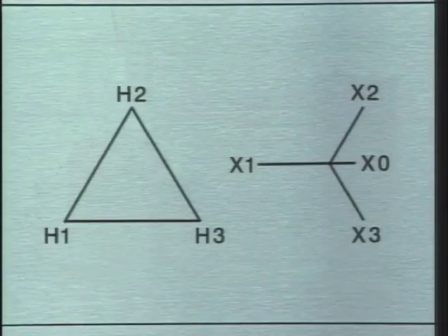In this part of the program, we're going to look at the principles for determining where to make the test connections to test the turns ratio of a given transformer. The transformer example that we'll use is a delta Y power transformer. The key to determining where to make test connections for a turns ratio test is on the nameplates of the power transformer. The nameplate contains a connection diagram for the windings of the transformer.